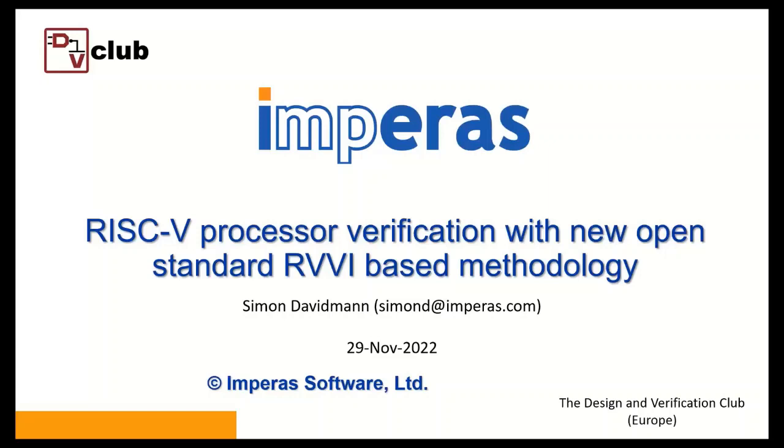But to answer the question directly, today, to do full functional verification DV of RISC-V, you need SystemVerilog capabilities to do with functional coverage and other things, and that does mean a commercial SystemVerilog simulator. But there's nothing specifically about RVVI. That is, RVVI works with Verilator as well as commercial simulators. But high quality verification is currently only done using commercial verification simulators, from Synopsys and Siemens.